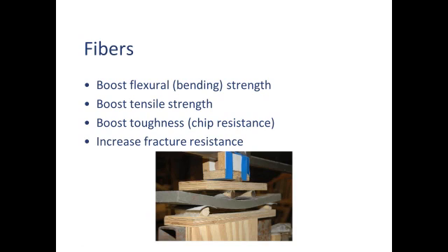That doesn't mean it's going to be chip proof. It doesn't mean we can make pretzels out of our concrete. But what you see there in the photos of flexural tests I did on some concrete, that's 5/8 of an inch thick, 16 millimeters, over a span of 10.5 inches. Don't know what that is in metric, 260 something millimeters. It's bending quite a bit with no visible cracks. That's what fibers can do for you.